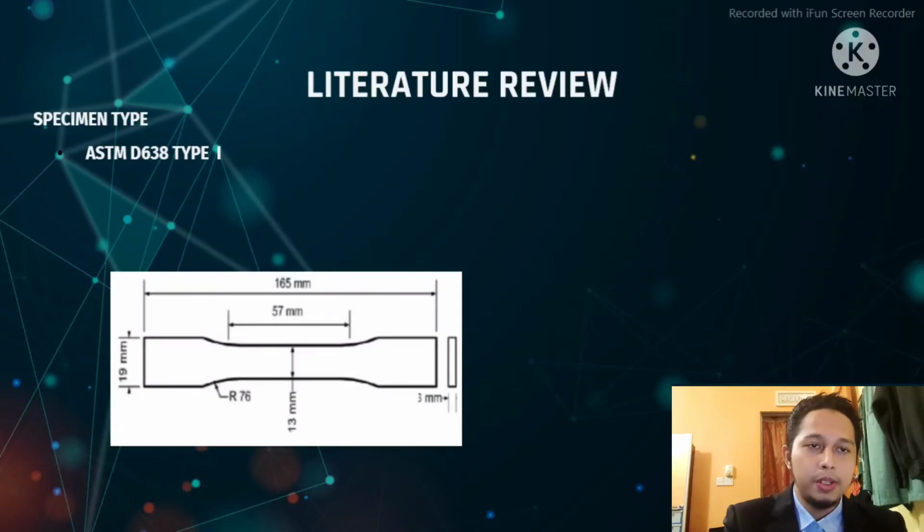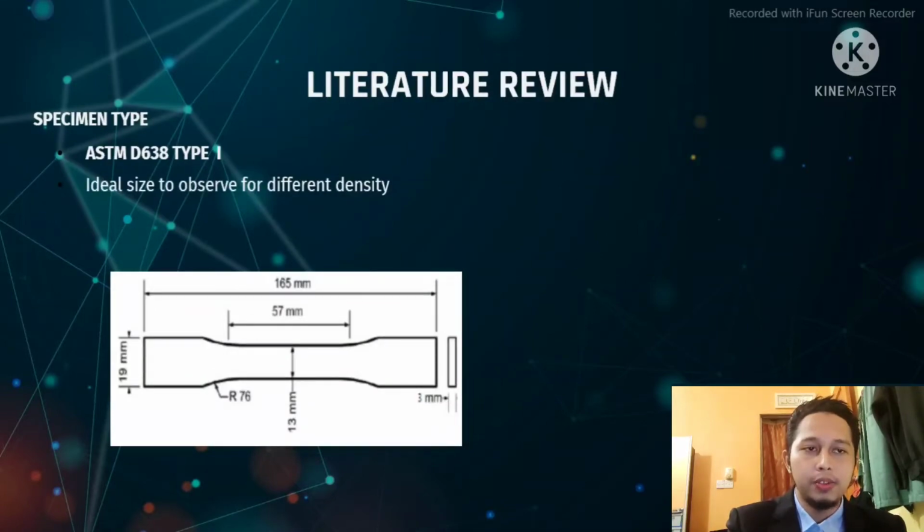The ASTM D638-14 type 1 was chosen as the specimen because it has a larger size. The larger size means that the infill pattern will be easy to model in the CAD software, and the ideal thickness will be easier to detect with the naked eye.